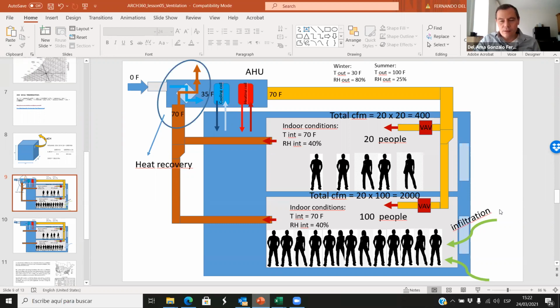And this is another field in architecture, about investigating if the building is working well or not. We have to do this by means of observation. We have to observe it. Okay, there's mold here. There's something wrong. We have moisture, and this moisture is creating this mold. Or we can test. We can use infrared cameras. We can take infrared pictures and say, oh, there's an issue here. It's latent, and we don't see that issue until it's too late.